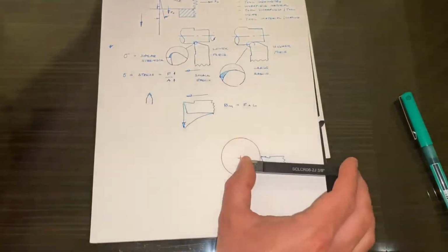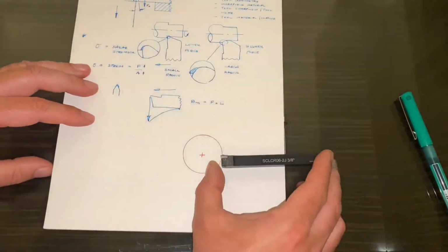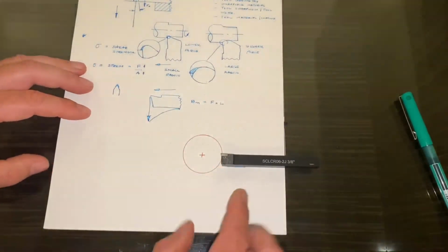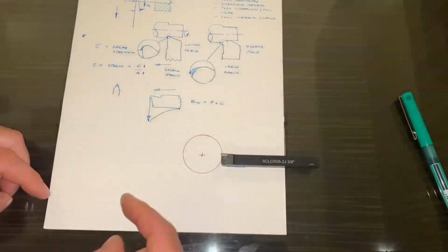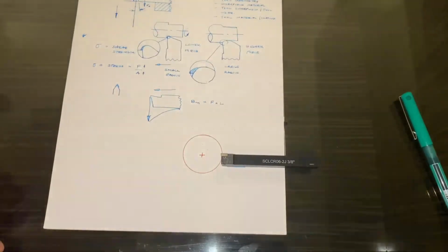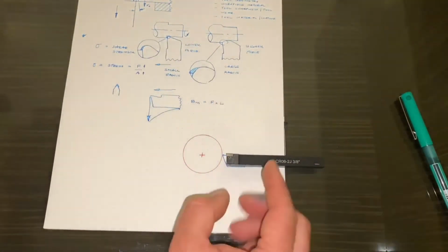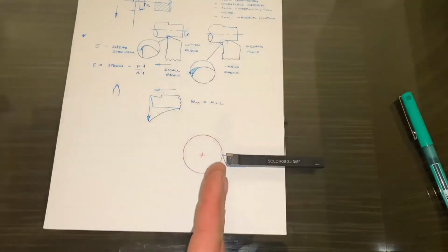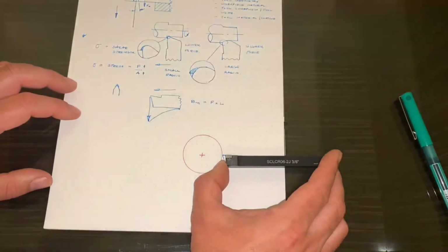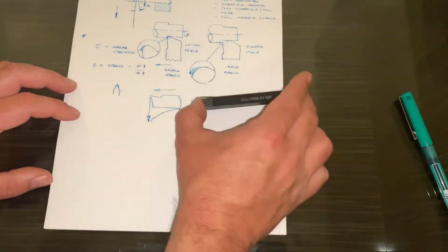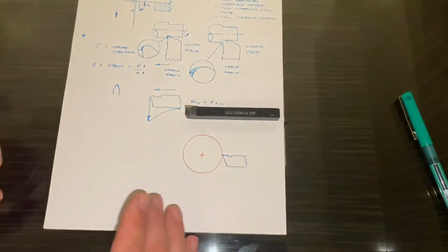We know in a static condition that there are various ways to measure this. We can measure the overall height, we can measure how well it is aligned to the tip of the centre. We can even put a rule in here and get it to line up vertically on the machine. There are methods that we can use, but what really matters is that the tool is at centre height during normal machining conditions.